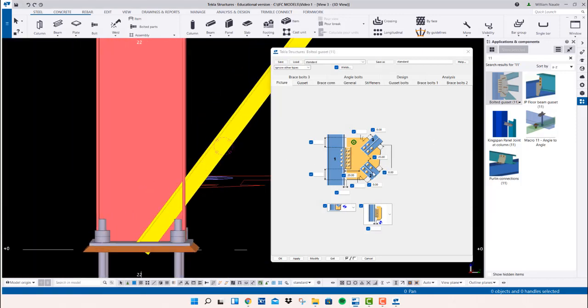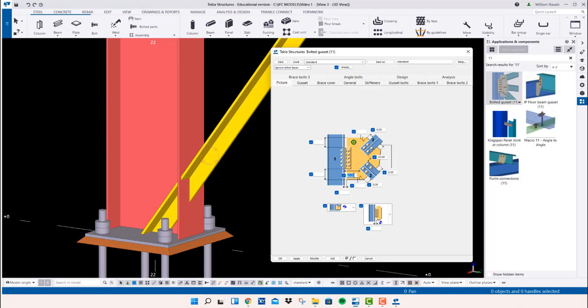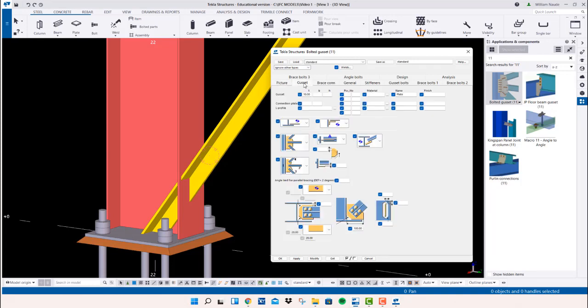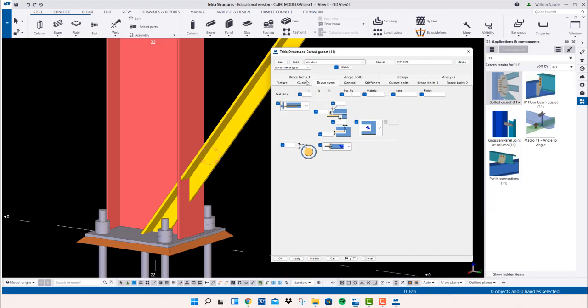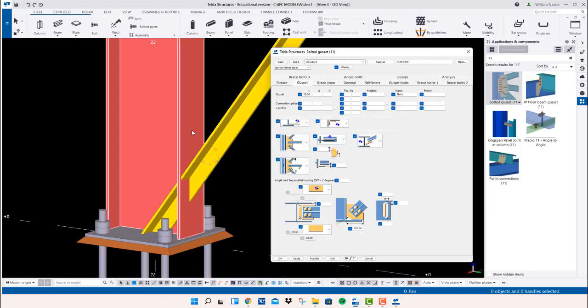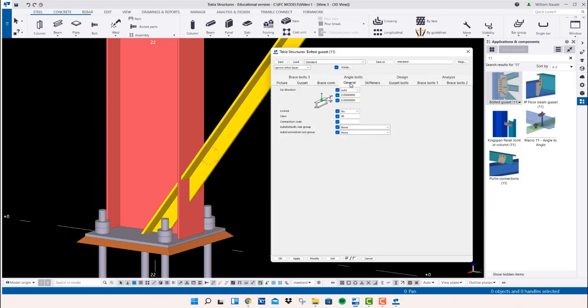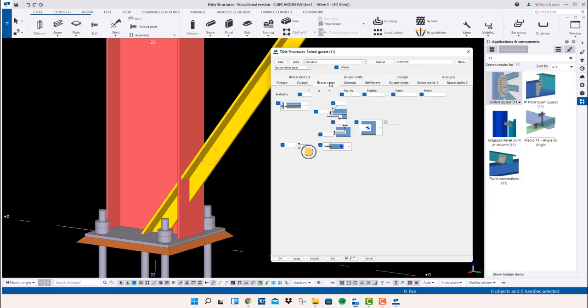This is the clearance between them, it doesn't really matter. You can use a 10 or 20 or 30 or 40 or 50, it doesn't matter. Again, play around with it. Now the gusset is 10 thick, yes, I'm happy with that. Now what this does is the breadth, we don't really do this. This is if you want to use an L profile, but again, very rarely used. The L profile is basically the gusset becomes a bolted connection to your column and no longer welded. Now, again, the color, you can change it as you see fit, it doesn't really matter what you want.